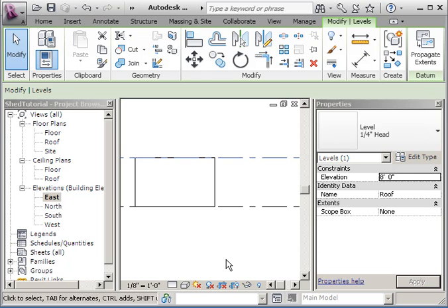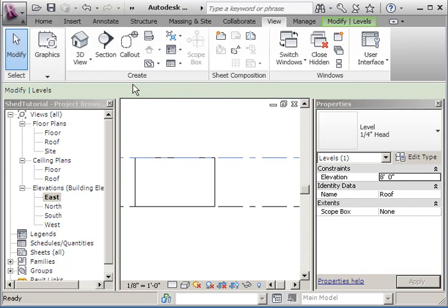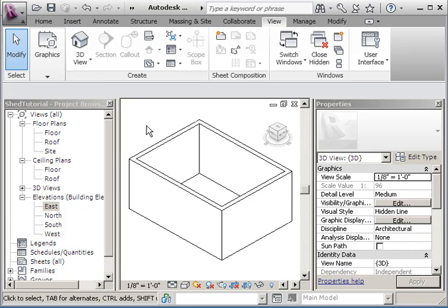So then we'll go down to step 5, which is talking about the cube. It says choose the view tab. So you'll click up here on the view tab, and you'll look at some of the ways of viewing your drawings. And it says select 3D view. That's right here. And when it becomes a 3D view, it gives you this view cube. The view cube graphically allows control over orthographic and perspective views of the 3D model. You have steering wheels, that's this thing right here, and you have the view cube.